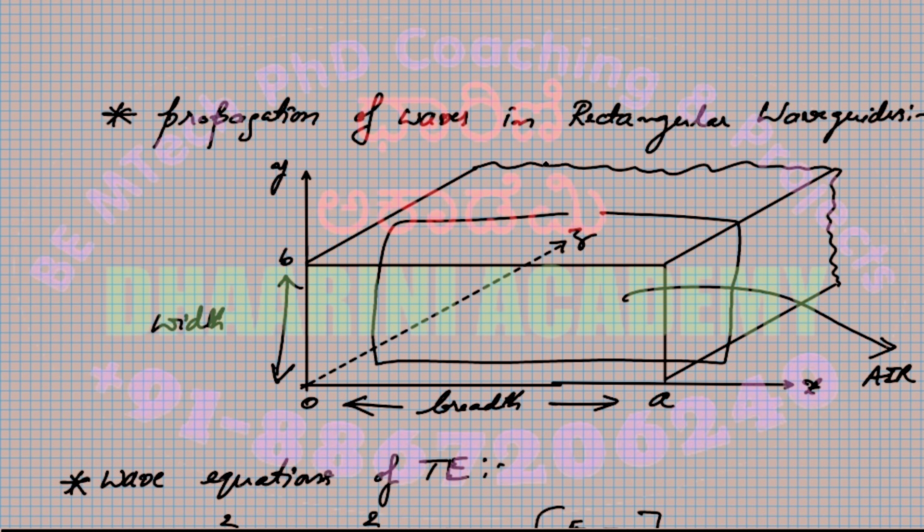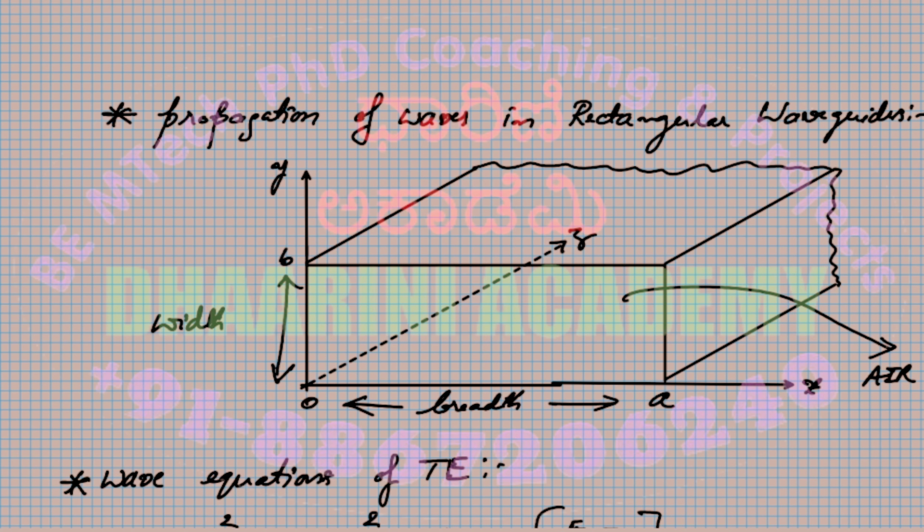If you take a path, you are able to move around that waveguide and come back, which means everything is shorted. That's why the entire surface of the waveguide is a short circuit. In other words, it acts like a ground for our electric field.